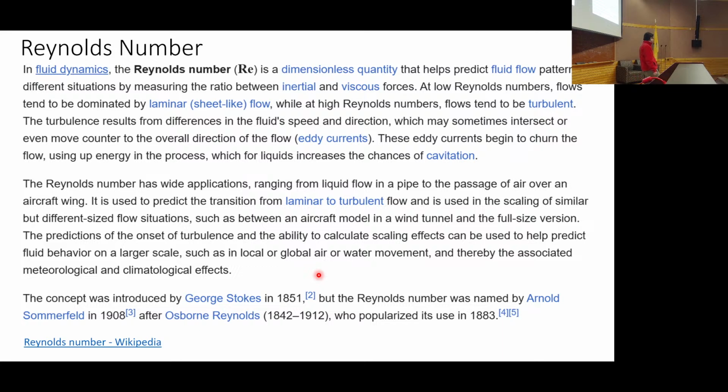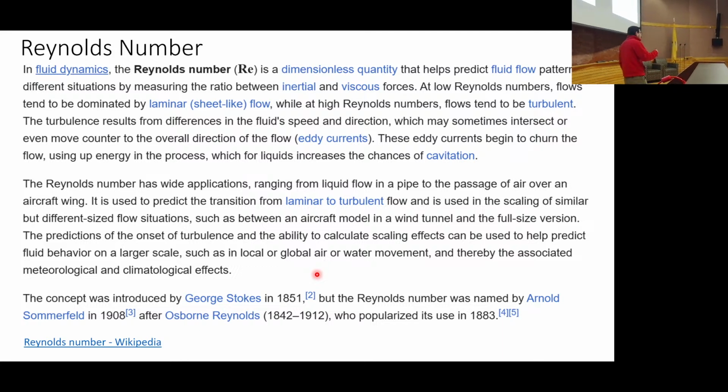What about you? I was going to say it gives me information on if it's laminar or turbulent. Okay, yeah, exactly, right? And Reynolds numbers are kind of funny because it depends on the geometry and the situation that you're using. Sometimes turbulent flow has to be hundreds of thousands, but in other cases it's like, oh, if it's above 600, it's turbulent, right? So it just depends a little bit on the geometry and the conditions that you're using.